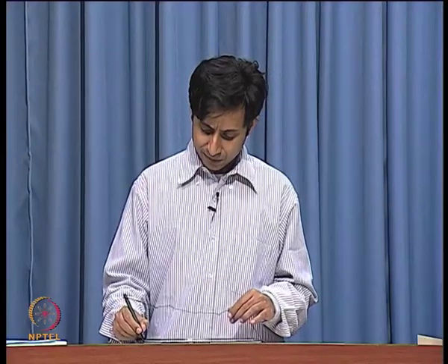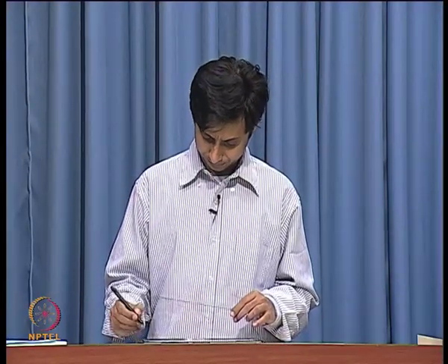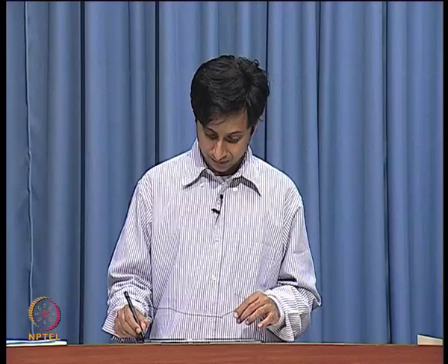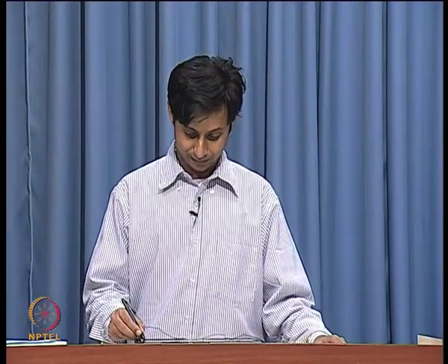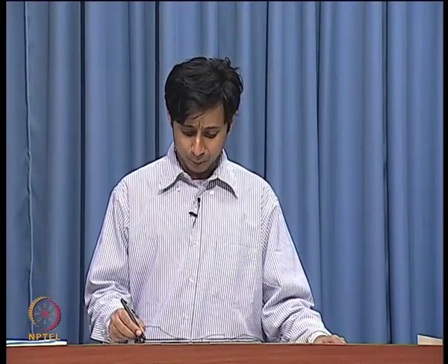All right. So, this is as far as our mixer discussion goes. This is how we design mixers. We make a double balanced mixer. For input matching purposes, you may or may not want to put that inductor over there, and you are done. The output of the LNA might not be differential. In fact, we did not design a differential LNA at all.